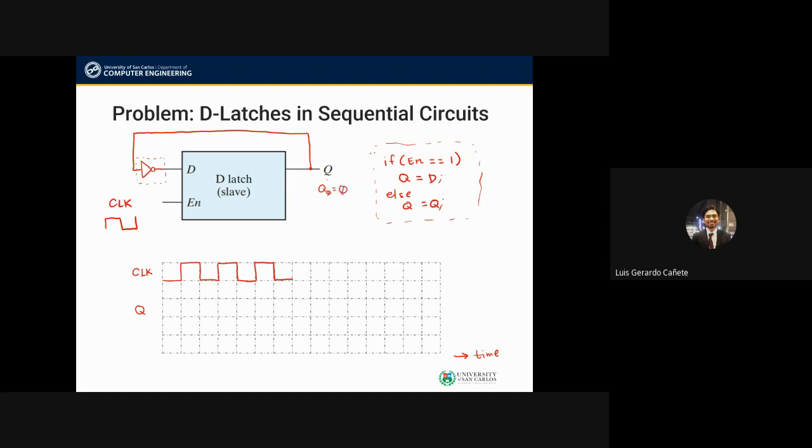I'm just going to say that by some random process, we turn on our circuit, and the value of Q is initially 0. So I'm going to have it at 0 right here. So if Q is equal to 0, then D is going to be 1, right? Let me write down the value of D here. So D is going to be 1 right over here.